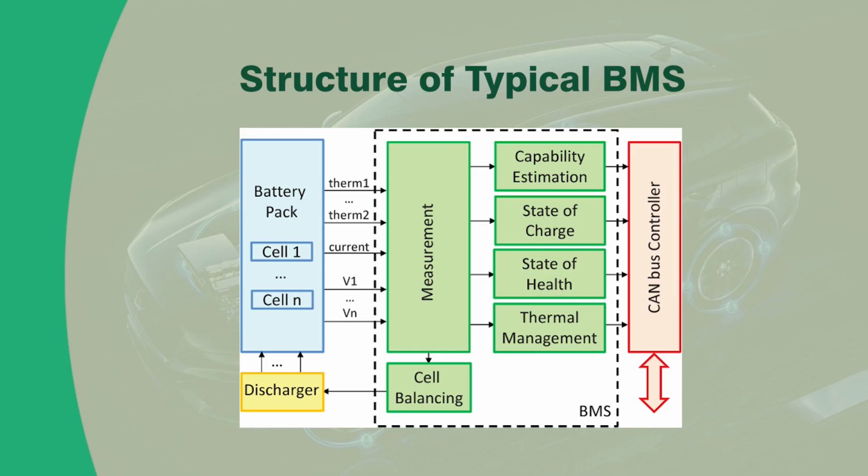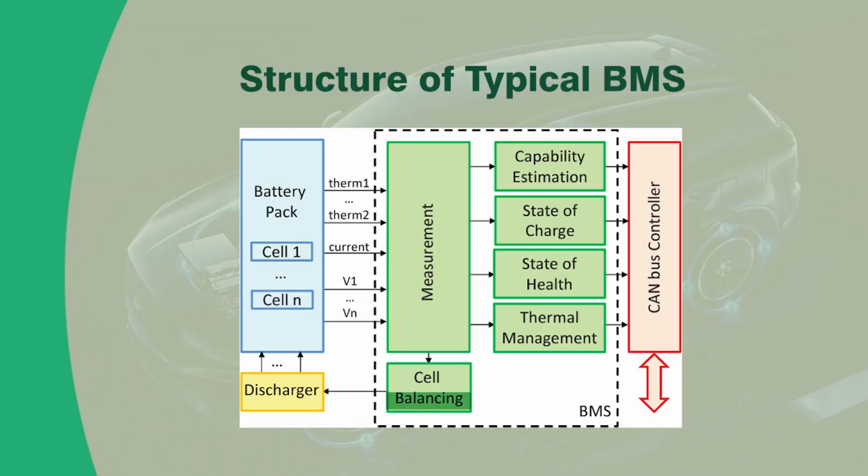The passive cell balancing is carried out by a simple shunt resistor. However, it is a cheaper choice, but at the same time the power dissipation is more in passive cell balancing. Whereas in active cell balancing, the cost will be on the higher side, also it will increase the size of the PCB, and at the same time it will reduce the power dissipation.